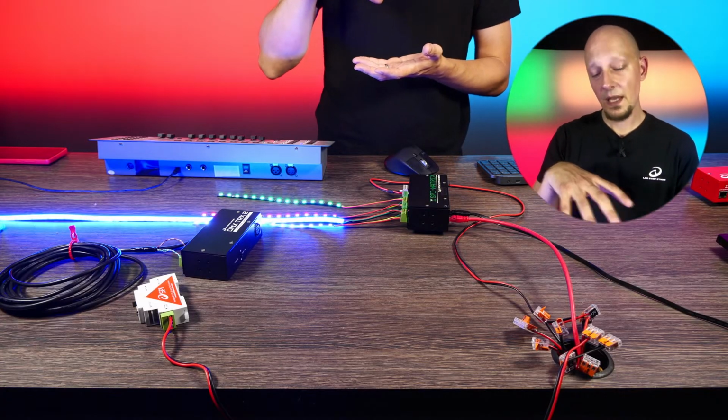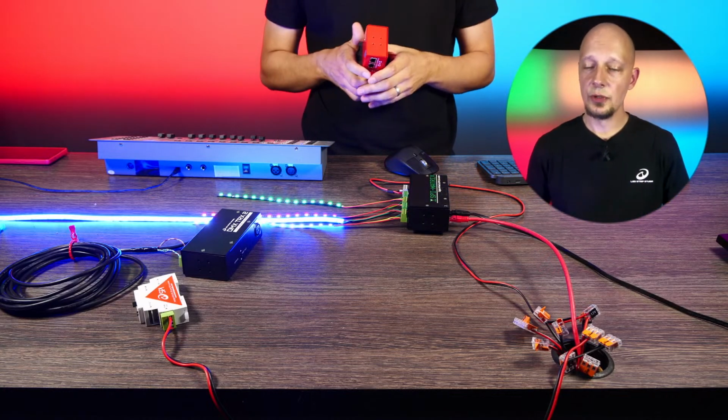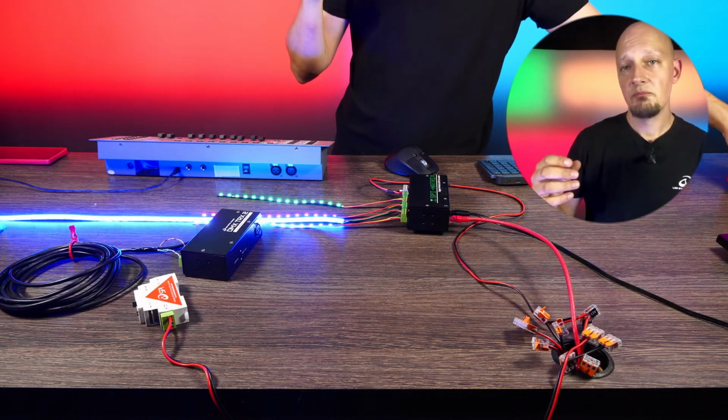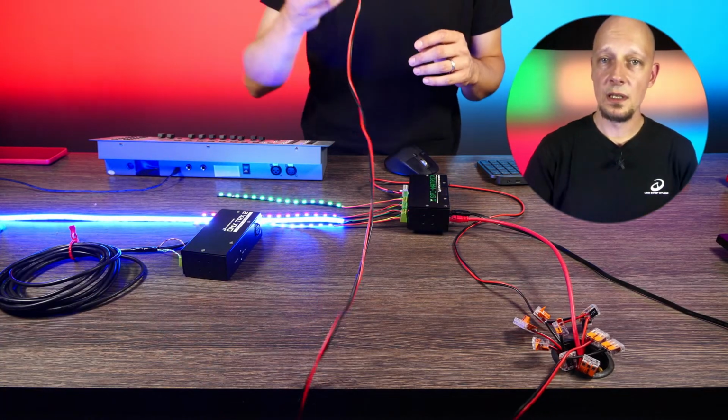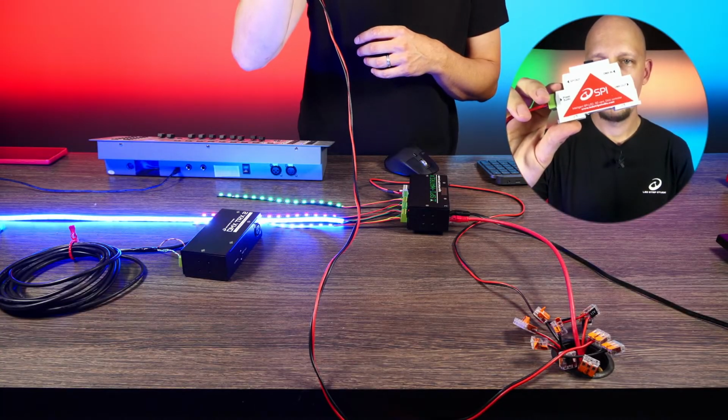So for the SPI matrix and LEC3, you've got an option to use the DMX. You've got a similar option for the SPI LED controller. This little device over here can control 1024 pixels, and you can use DMX to trigger the effects. You can also use DMX synchronization with this controller, so you can have multiple SPI LED controllers in a single row, and you can synchronize the content over multiple devices.